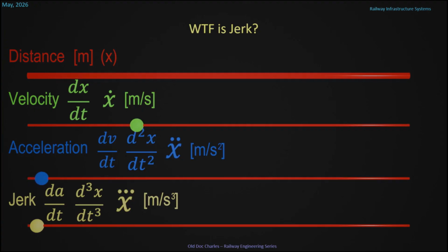Now, jerk is important for passenger comfort. Passengers can tolerate acceleration, but they don't like to be jerked. So there are limits on the maximum jerk that you can apply to a passenger. And whatever railway administration you work for, there will be a standard somewhere that gives you that information.